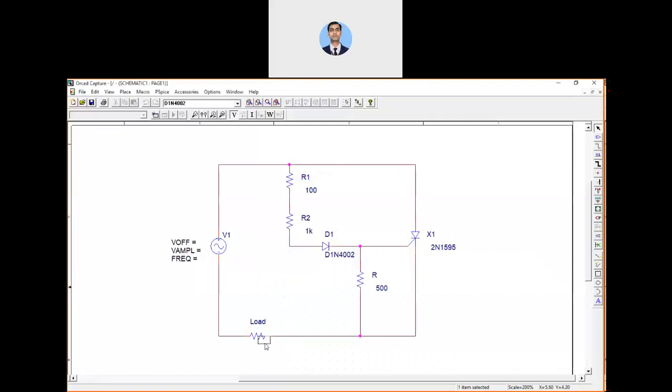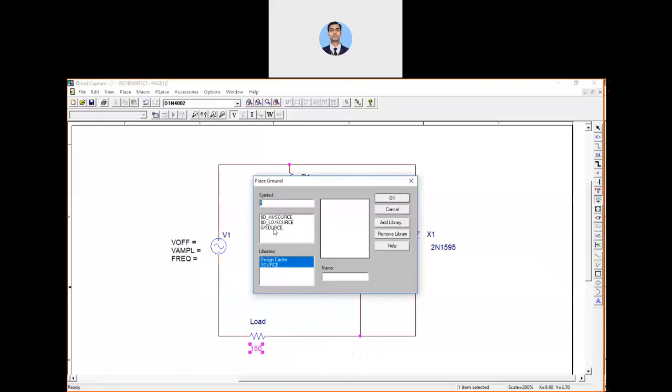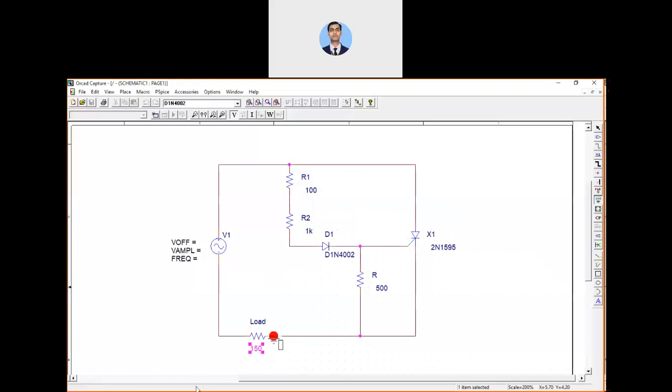You also have to connect a very important thing, ground, zero source. Otherwise, if you do not connect this one, when you simulate, your project will say every terminal is floating. This actually provides the reference node to your project, so that it will connect properly.